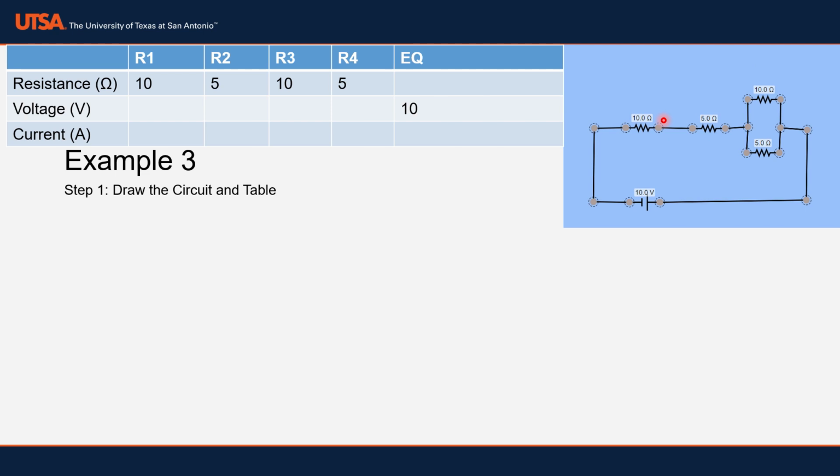So now you might be thinking, what do we do? Well, it's going to be the same thing. We're going to have to calculate our equivalent resistance, okay? But we're going to have to do a few extra steps now. And this is why I stress it's very important to draw your circuits out. Okay, so when I'm looking at this, the first thing I say, and you could go the series approach, you could add these two up, but the first thing I look at is I want to deal with this parallel part because I don't like looking at this parallel part.